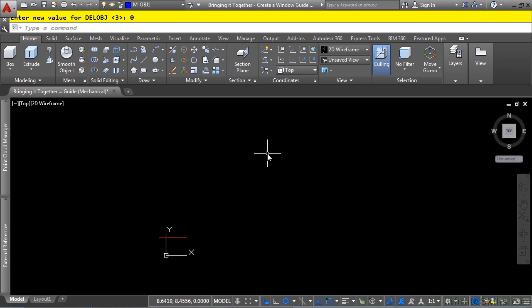Now, when creating 3D solids, you have to think about the space that you're in and the plane that you're at before creating it. If we were to draw the 2D profile in this view right now, we are in the top view of the WCS, which means that if we eventually extrude this, this will go straight down into the ground, into the actual file. Since that is not the preferred method, let's set our UCS so we're actually in the front view, and then we can extrude it in the top plane, which is a better way to 3D model.